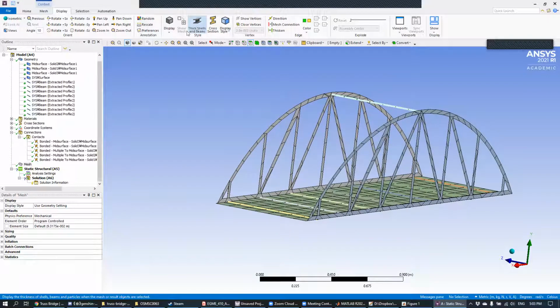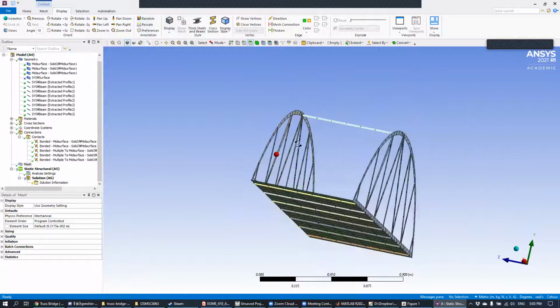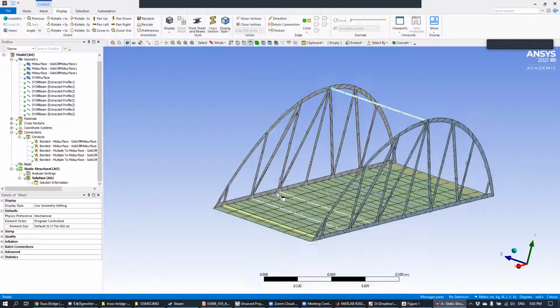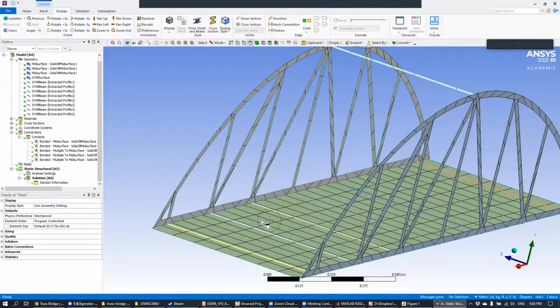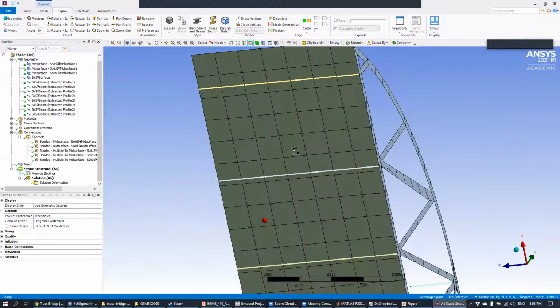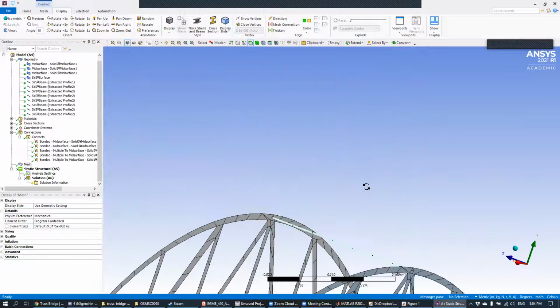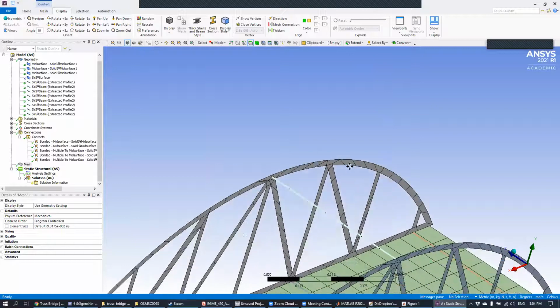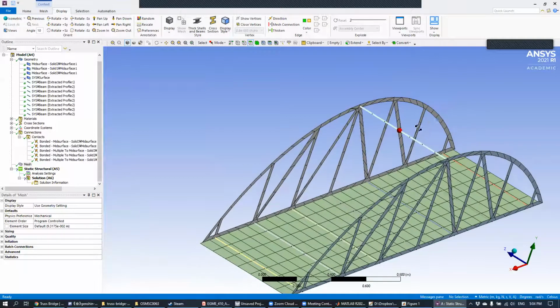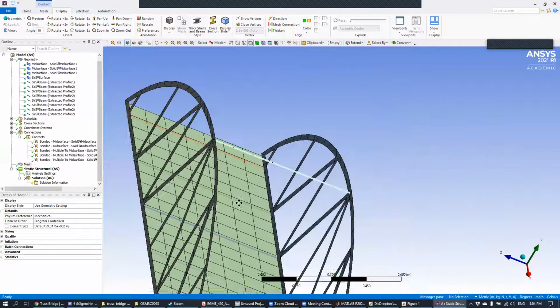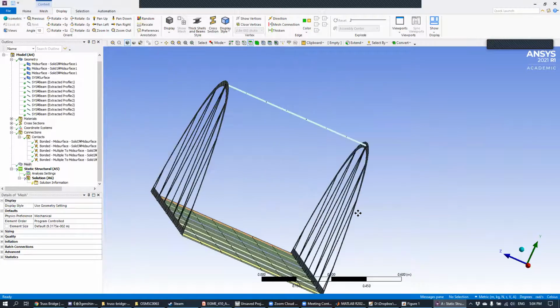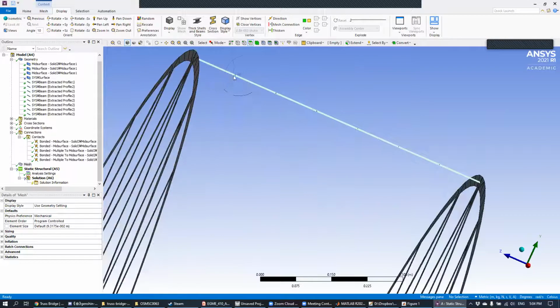I think it might be enabled by default, but if you turn it off, then you can see that Ansys is creating these 1D and 2D elements. If you look at the road, the road is basically just a giant rectangle. All Ansys did was fill it with quadrilaterals, so we've really made 2D element types out of these. And our beams are just 1D elements. Just for rendering purposes, it added some thickness here, but you can see that it looks like just one-dimensional stuff.